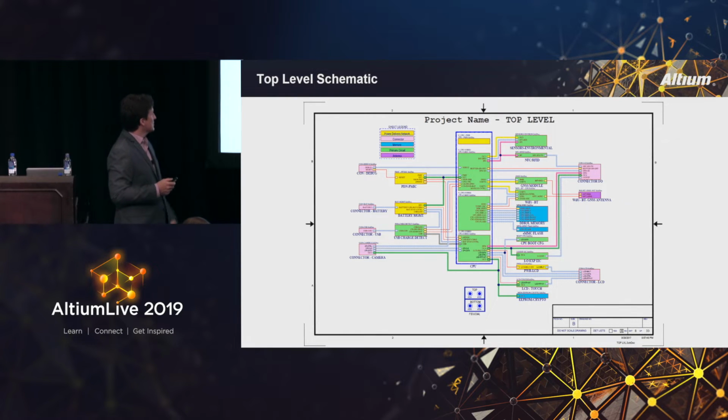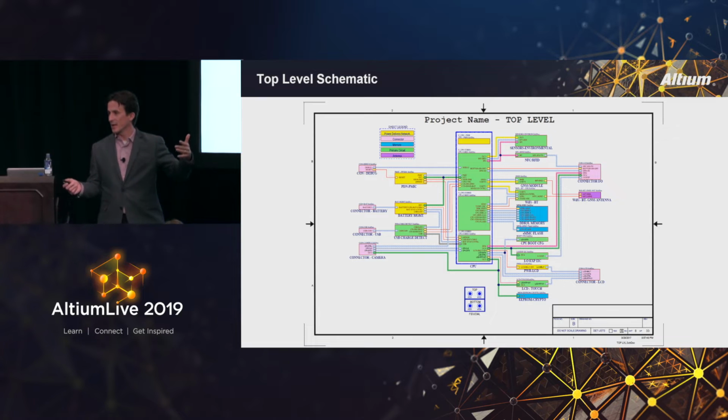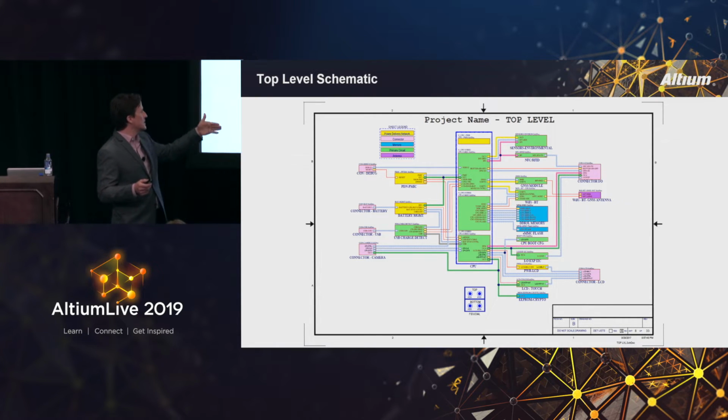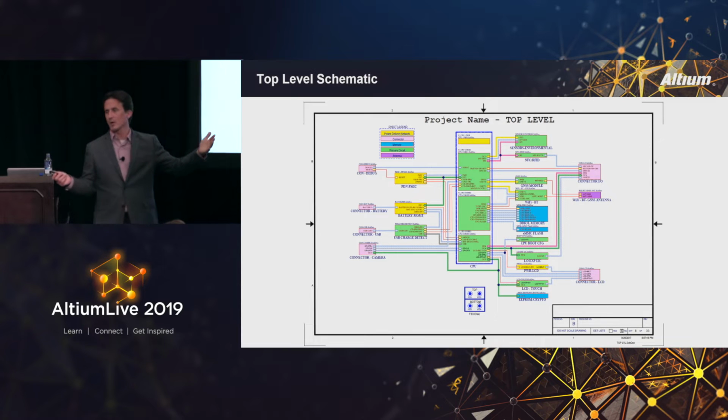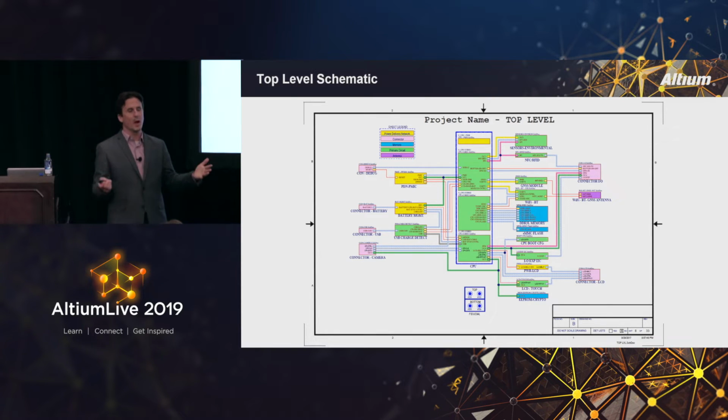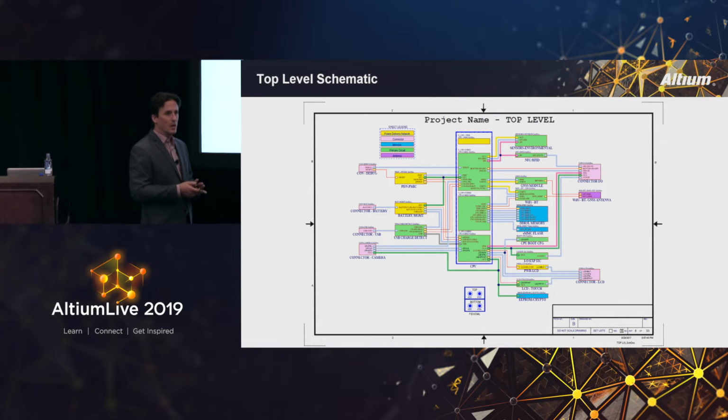So, yeah, this really lends itself, and let me talk about the other critical things that I'm looking at here. As I go into my PCB layout, I'm placing my connectors almost first. The other thing that I'm easily identifying in here are my critical buses. So what are my high-speed buses, and how are those connected in the design?